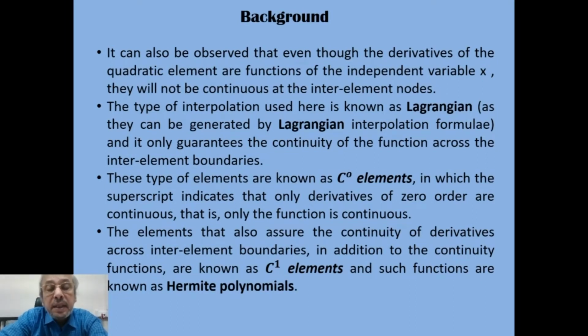And this guarantees continuity of the function, that is the dependent variable, across the interelement boundaries. So these types of elements are known as C0 elements, in which the superscript indicates that only derivatives of 0 order are continuous. That is, only the function is continuous.